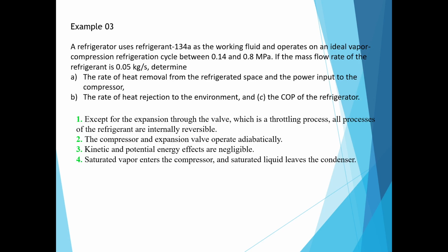The first assumption is, except for the expansion through the valve, which is a throttling process. If you remember, we have four components: compressor, evaporator, expansion valve, and the condenser, right? So for the expansion valve, we assume that the process is a throttling process, therefore there's no heat transfer and also no work involved, right? And the whole process of the refrigerant is internally reversible.